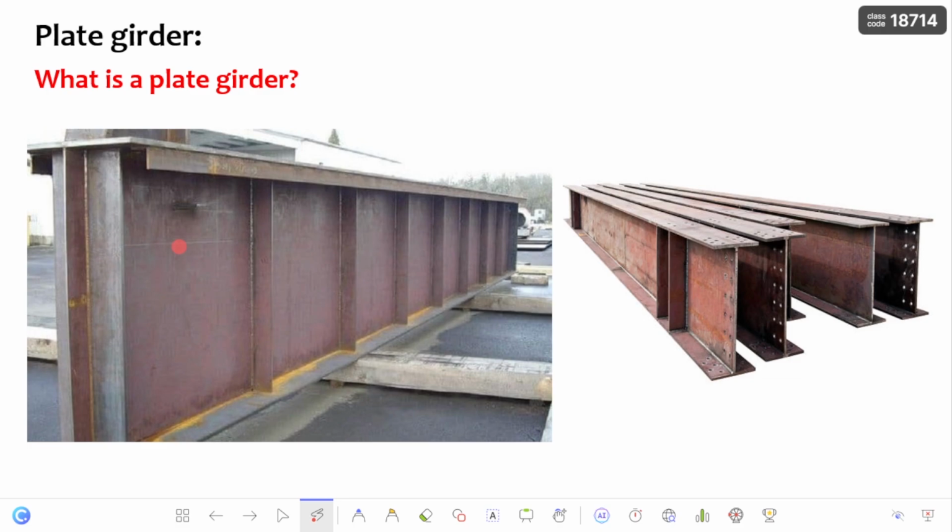And these are deep flexural members which you use to carry heavier loads, and also at larger spans you are going to prefer this plate girder. Coming to the advantage of this plate girder, it can be shaped to match the bending moment curve itself, and you can place the exact amount of steel to match the bending moment or shear force coming onto the structure. For example, across the length, if the bending moment is increasing, you can place a tapered section across the length. In this way you match the requirement of steel at the location.